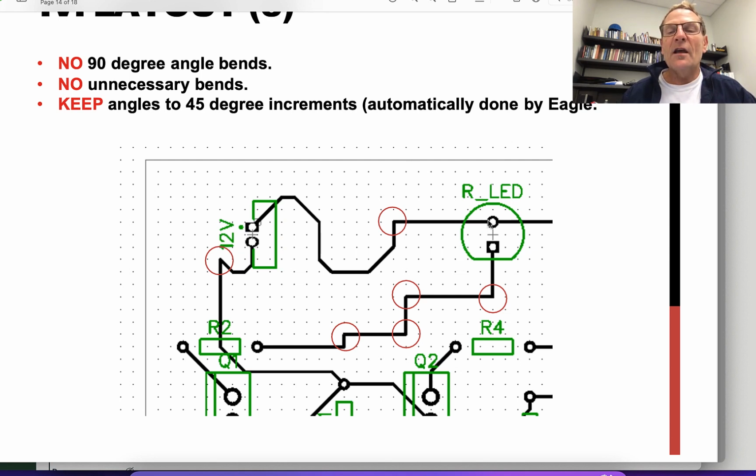If you imagine a moving alternating signal moving down this line and it runs into this right angle, part of that signal will reflect back and some of the energy will be lost. Whereas if we have an obtuse angle, most of the energy of that signal is not lost in reflecting back, but rather continues forward on its path towards its destination.